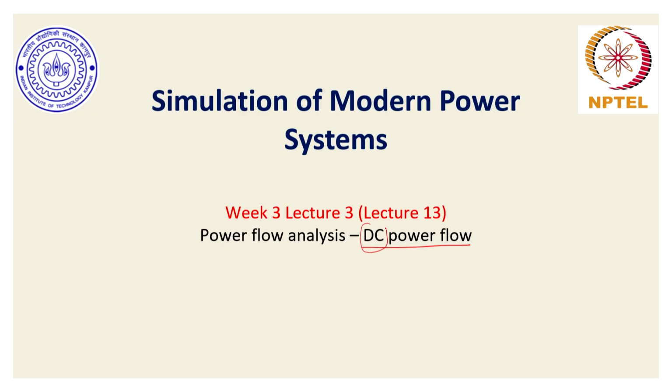It is not an exact or accurate technique like fast decoupled power flow, Newton-Raphson power flow, or the Gauss-Seidel method. It is a very approximate technique. It's a linear technique, which is where the term DC comes in. For DC circuits with known voltage sources or current sources, the corresponding circuit equations tend to be all linear simultaneous equations, and there is no recursion or iteration involved.